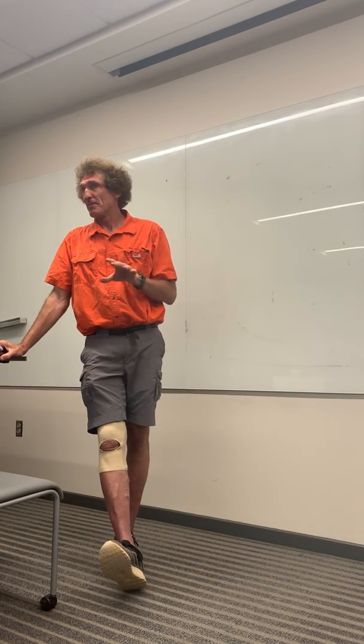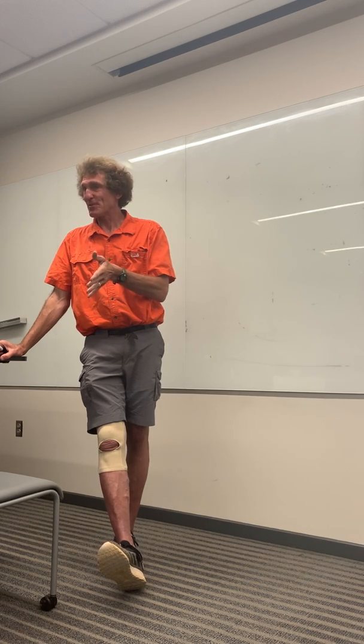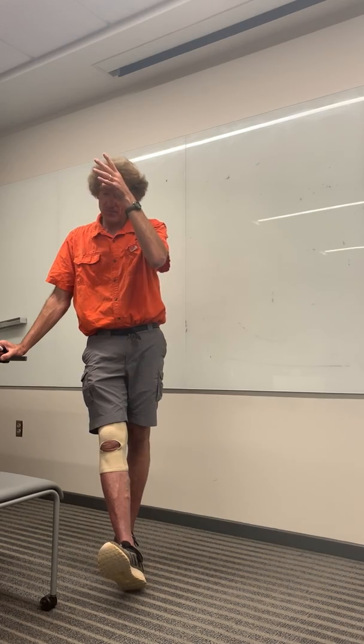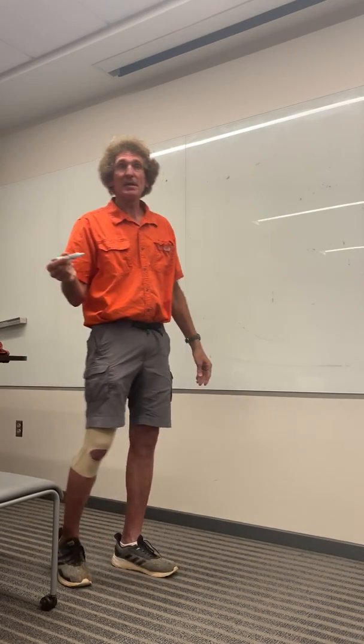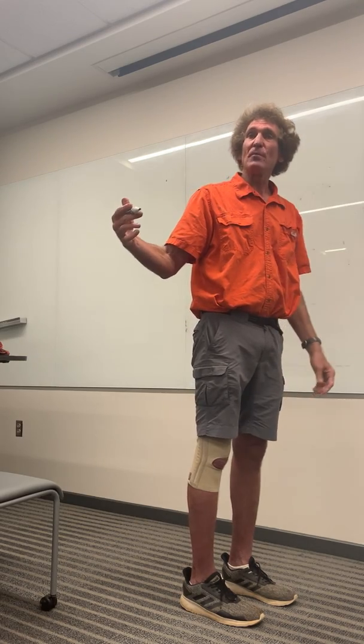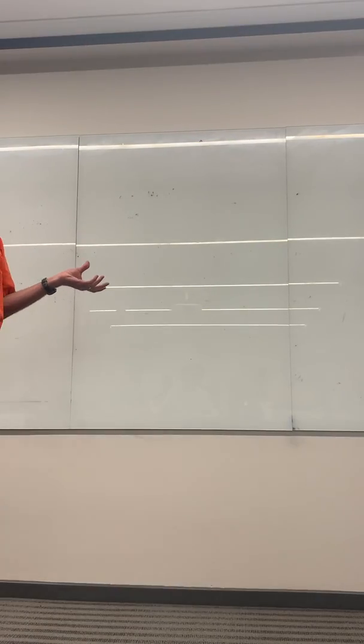But that's my story on why VSWR is very, very important, because that antenna wouldn't work at all with that VSWR of 4. Now, getting back to this thing, when we do matching, that's the way we get rid of problems that would be impedance mismatching. Like you get a load of 100 plus j60 and you've got 50 ohm cable, that means you're going to have a lot of reflections. So how do you get rid of the fact that you're going to get a lot of reflections? You do impedance matching. And here in a nutshell is what it is.